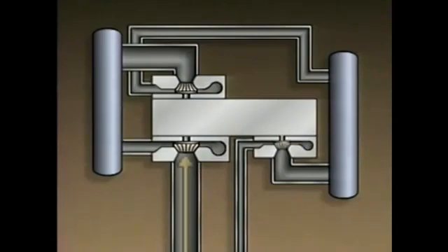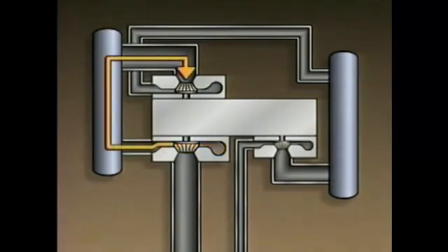During operation, gas enters through the suction line into the first impeller. The gas passes through this impeller and the associated volute where its pressure is increased. The gas is then directed through an intercooler. The intercooler is a heat exchanger. The intercooler removes heat from the compressed gas. The gas is then directed into the second impeller and second volute where its pressure is increased even more.